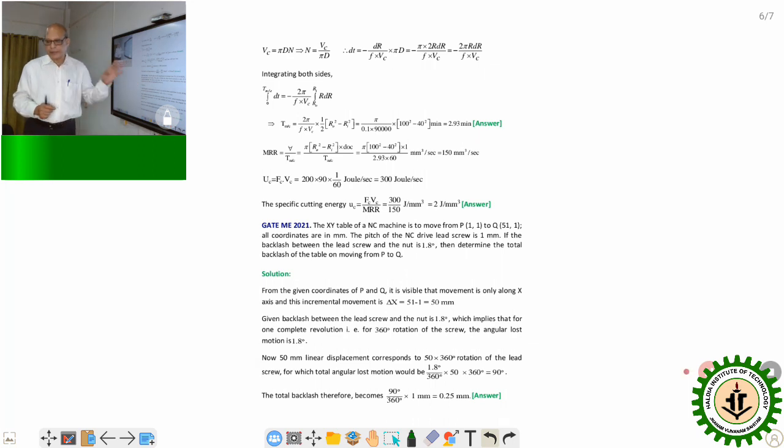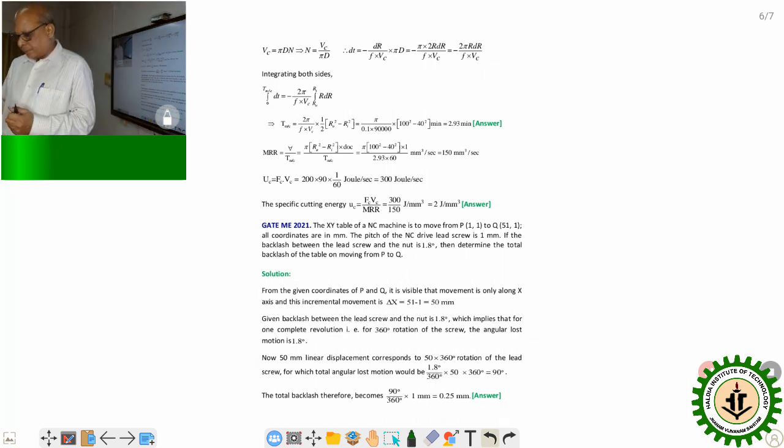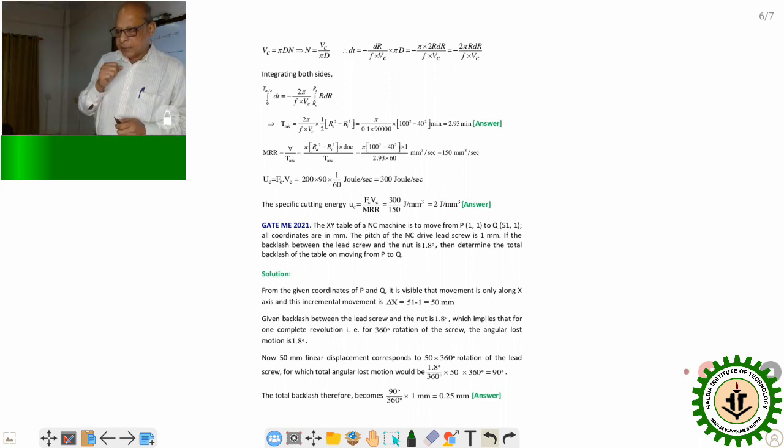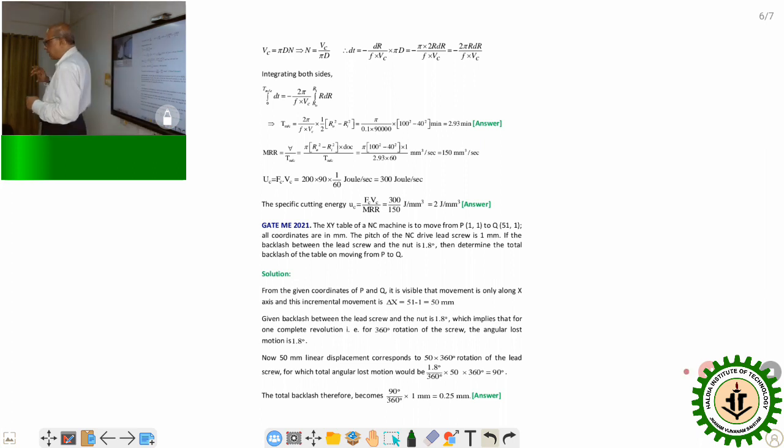This problem is a little bit unconventional. If you can recall the sources of inaccuracies, then you will find in our discussion earlier that play between nut and bolt, that is due to wear and tear for prolonged use, backlash in the gears, misalignment, all these contribute to the inaccuracy, which eventually deters the system from achieving the final desirable position.